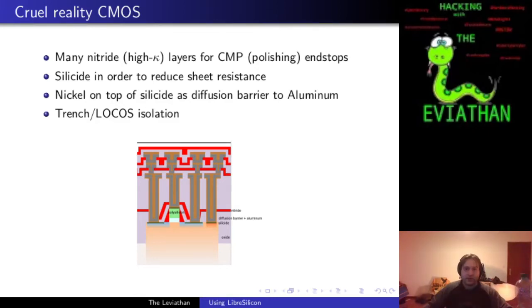You have to use a layer of protective silicon nitride, which serves as an end stop for the polisher, by making use of the fact that the selectivity from low-temperature oxide to nitride is between 100 to 1 and 1000 to 1, depending on the density of said oxide.